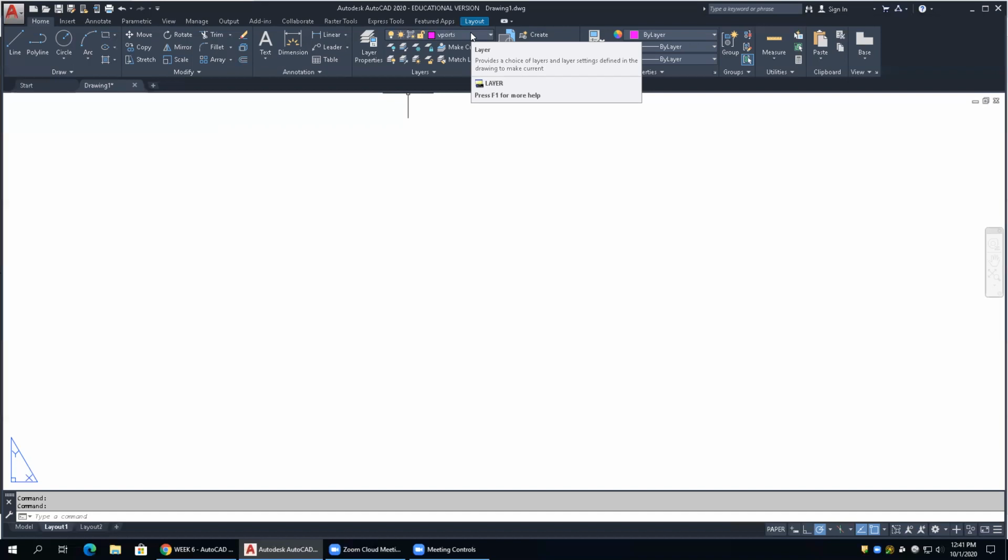Okay. All right. So we're going to create objects. Basically, they look like rectangles. The command we're going to use is called mview. So you just type in mview. I think actually you can just type in mv, but let's go with mview. And then hit enter. So this has a bunch of sub options, and we'll take a look at these sub options in a minute.